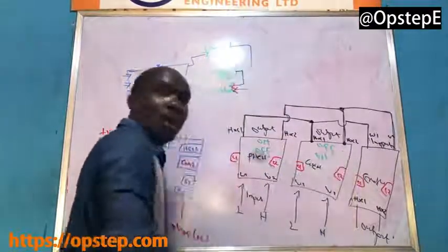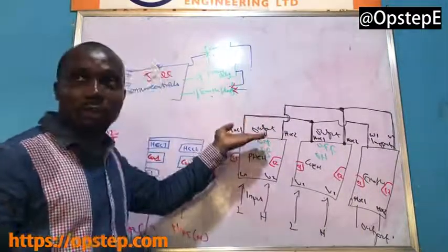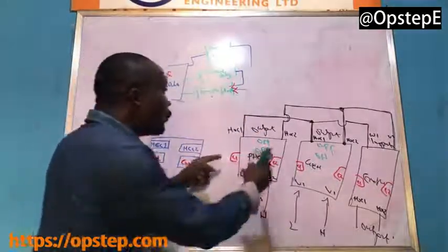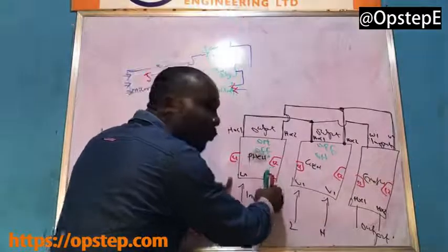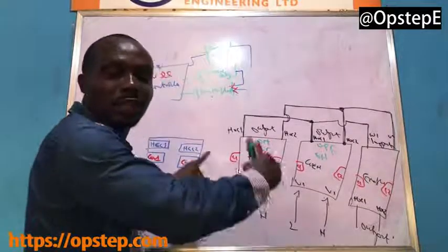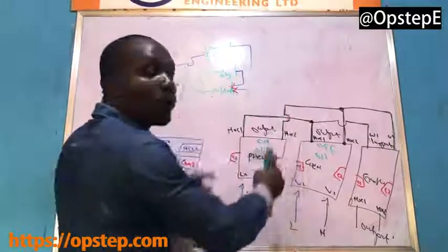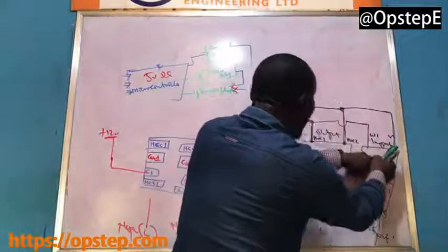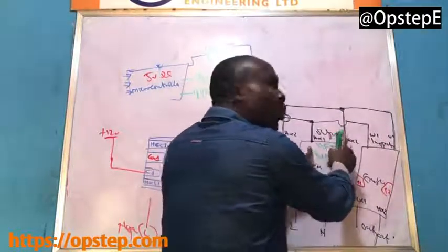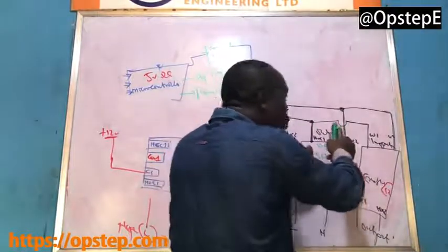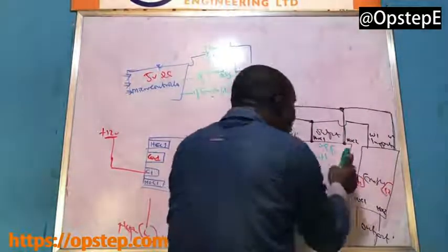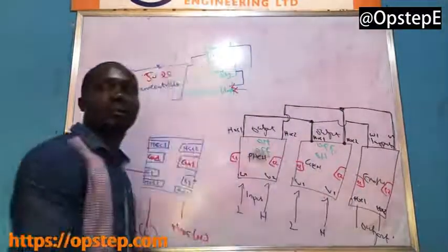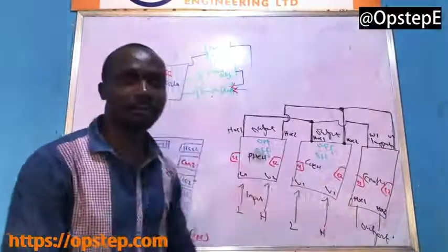So this is what happens. When NEPA is on, so NEPA is available, and you energize this coil, the voltage that is on your wiper, that was previously impressed on your normally closed contact, leaves the normally closed contact and switches to your normally open contact. So the voltage is here. So the voltage travels through here to this place. Don't forget this guy, you can see it. But this guy is not going to react because that voltage is on his own normally open contact. Why? The voltage that is here, the coil is off, is on his what? Normally closed contact. Okay. So there's no way they can jam.